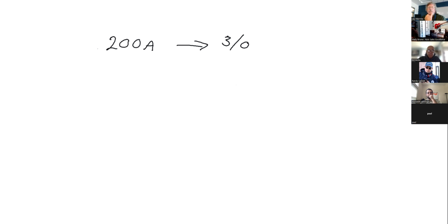I don't know if I reproduced the aluminum part in the book. No, I just have copper. Yeah, so you might end up with 4/0 aluminum, which might be a lot cheaper. So that's an option. Yeah, 4/0 wire or even 3/0 wire running 600 and some feet is pretty expensive. So you don't want to run 2 of those. Exactly.